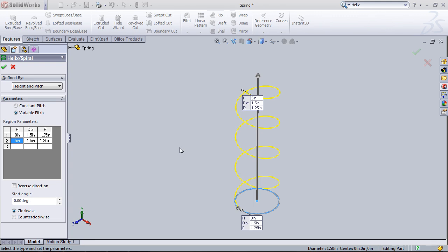One thing to notice here is that while this forms a perfect helix, it's actually not the shape of a typical suspension spring. Springs in a suspension system will coil tighter at the top and the bottom and have a variable pitch. This enables them to be cut off and then have a much flatter surface to push against.